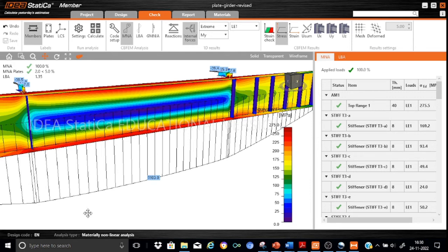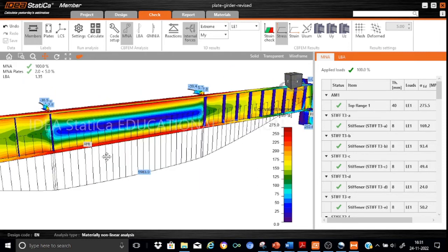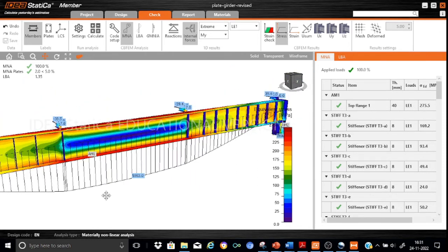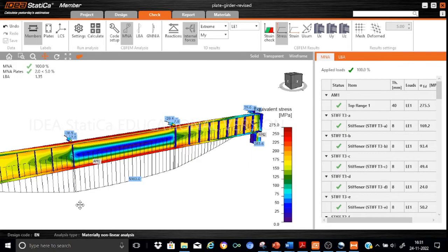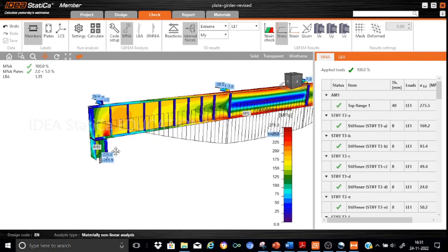The reason is simple: the bending moment will not vary that much. We also find that towards the web, the stresses are diminishing. It is somewhere between 0 and 50, and this is our expectation also. Now let us see some other concentrations where the stresses are likely to exceed. Obviously, one such location is the support.